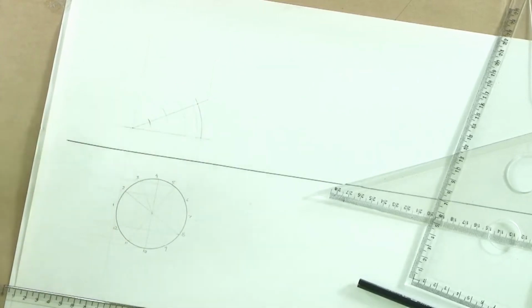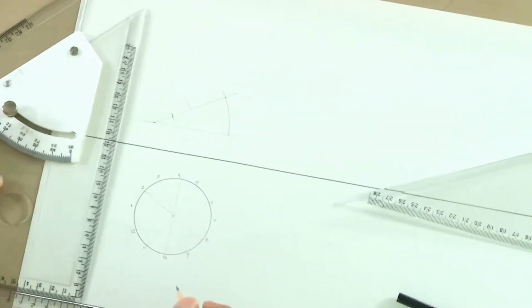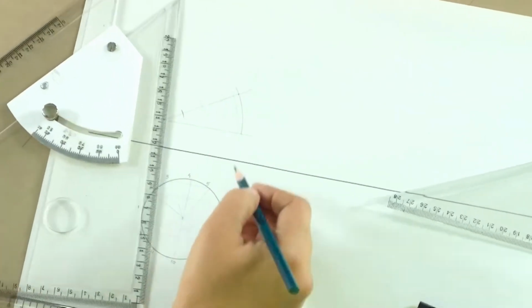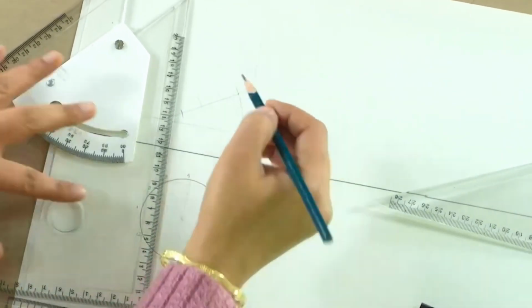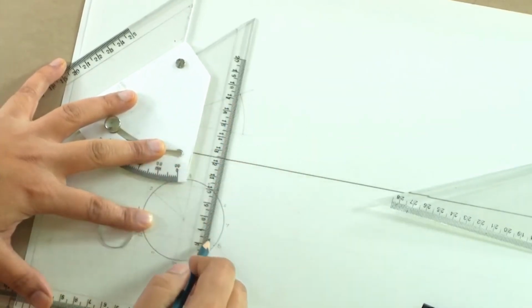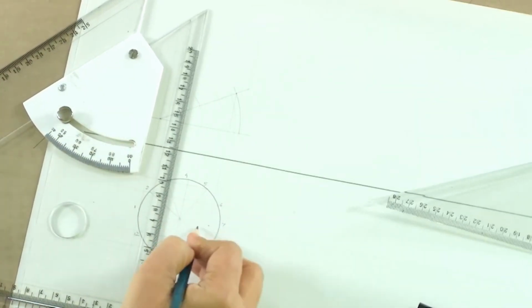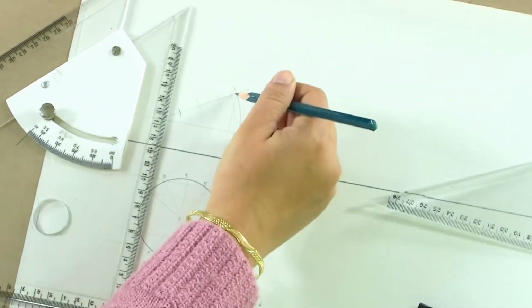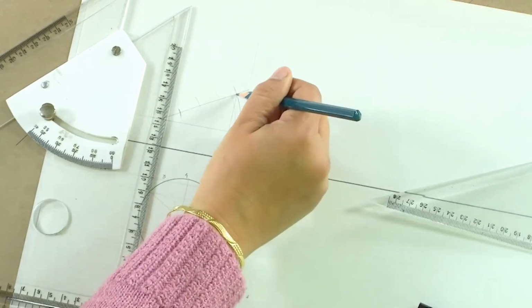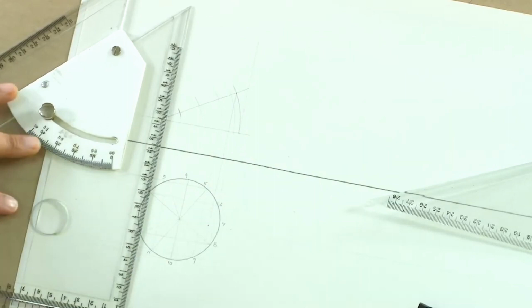The final projection is going to come now. Now we will bring back the projection of these points. So we took 7 here, now 7 went up there and it is coming down. When it comes down, 7 meets 7 again. So the horizontal projection remains the same. The vertical projection has shifted from this point to this point, which is what we get. So this is the point 7 now.